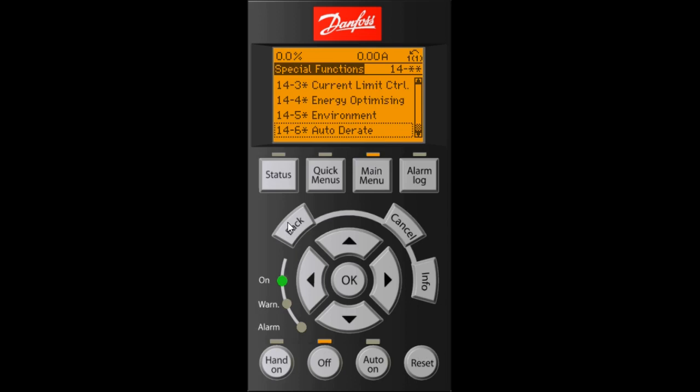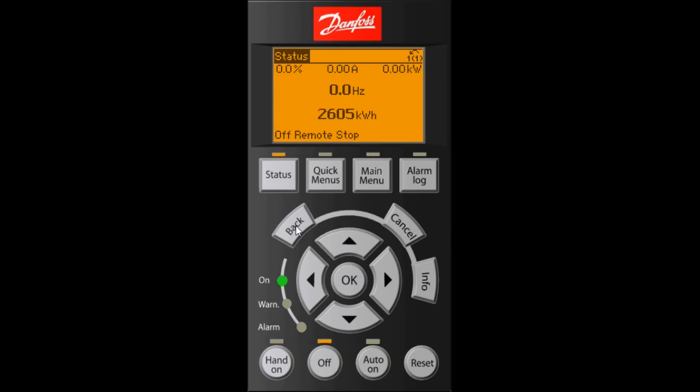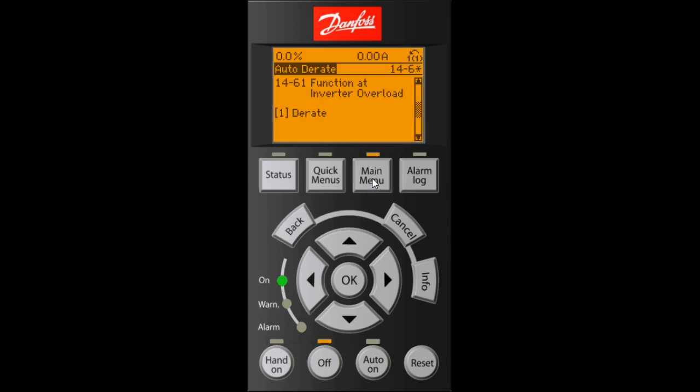You have now put the recommended base settings in for the inverter to work in manual operation. Now we will put the parameters in for the VLT to work on a 0 to 10 volt signal from a climate controller. In this instance we are using the Dalton Dairy Bravo Touch. Step 1. Go to 6-00, Live Zero Timeout Time.